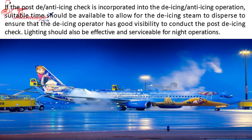If the post-anti-icing check is incorporated into the de-icing/anti-icing operation, suitable time should be available to allow for the de-icing steam to disperse to ensure that the de-icing operator has good visibility to conduct the post-de-icing check. Lighting should also be effective and serviceable for night operations.